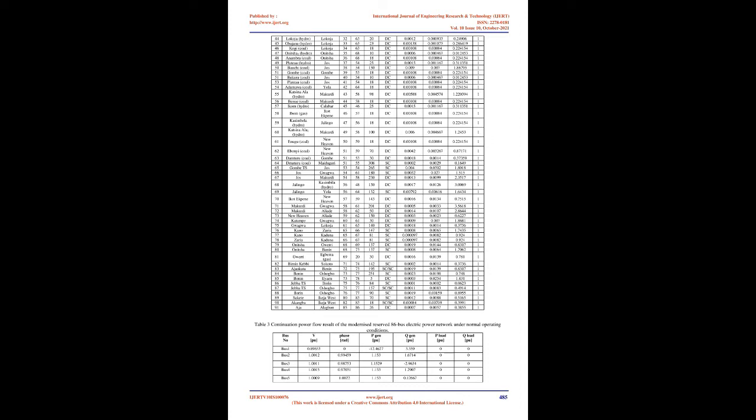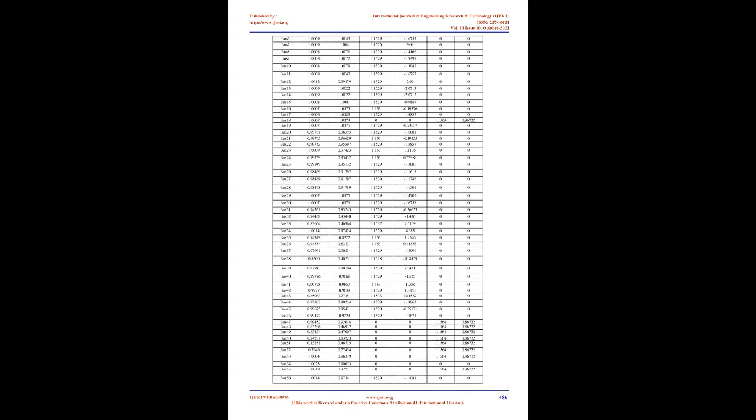From a known initial solution, a tangent predictor is used to estimate the solution path for a specified pattern of load increase. The corrector step then determines the exact solution path using a conventional power flow analysis with the system load assumed to be fixed. The voltages for a further increase in load are then predicted based on a new tangent predictor. If the new estimated load is now beyond the maximum load on the exact solution path, a corrector step with loads fixed would not converge.